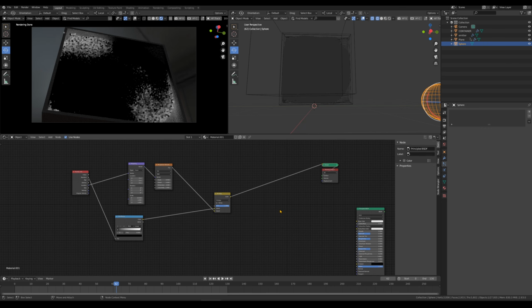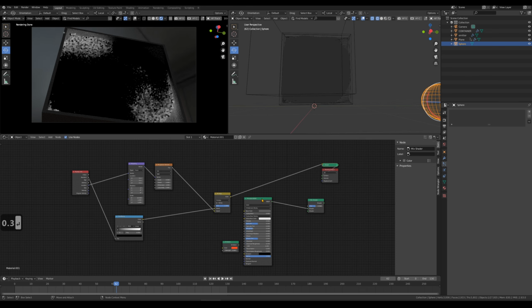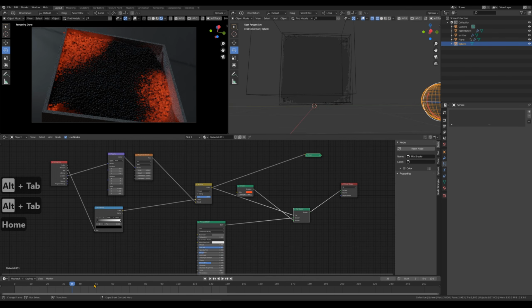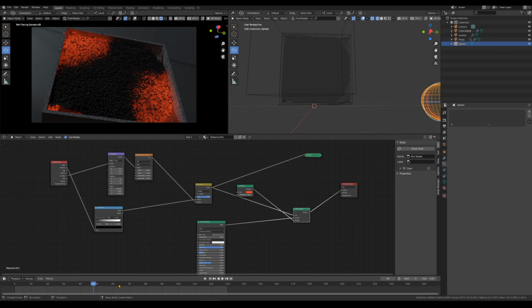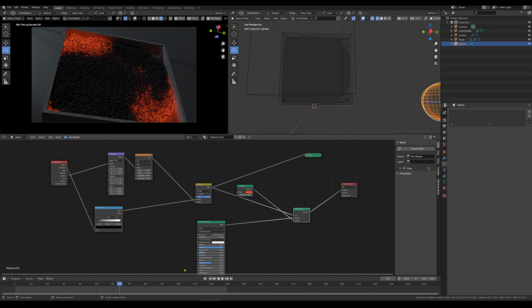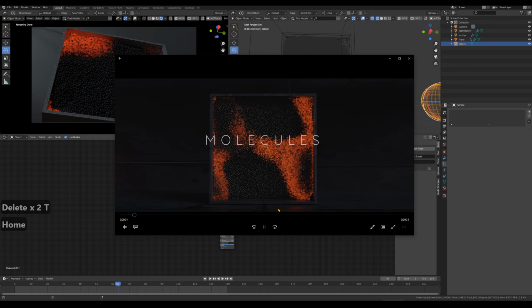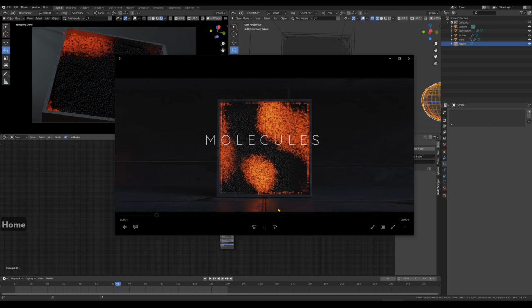Next I'll do the same thing I did in the previous shot. So I'll grab a mix shader and the emission shader, make it all desired color, and I'll mix between the BSDF and the emission using our newly created mask. And if you see that plugged into the surface, there you go. So now we have our baby musky texture in on our particle system, which evolves and moves as our particles move, So yeah, that's how I created the simulations for the video.